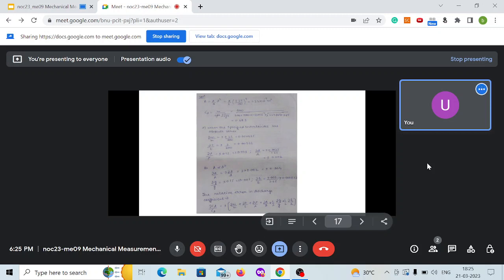And then the uncertainty for diameter. In the case of area, you have to find the uncertainty from diameter, which is 0.002. If you differentiate area with respect to diameter, we get dou A by A is 2 times the change in diameter by diameter. So the area uncertainty is twice the diameter uncertainty, so plus or minus 0.004.